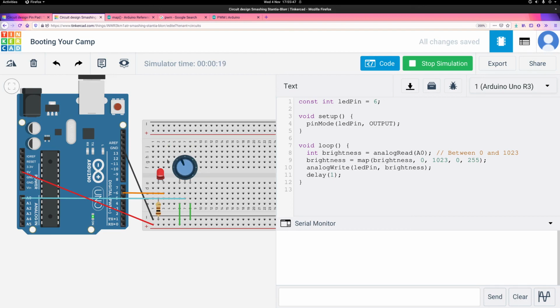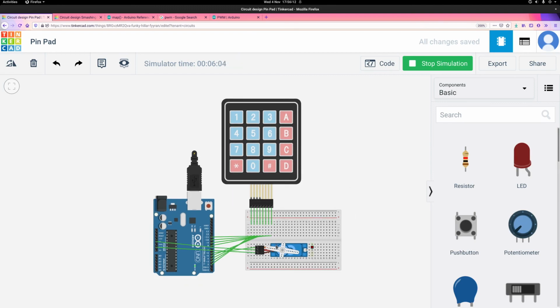Now, there's also probably a way to build this particular circuit without an Arduino. But we've seen already how you can use the Arduino to do more complicated things with the numbers you're receiving here. So, for example, you could use this number that you get from the potentiometer, this value that you twist. You could convert from this big range up here of 1023 into a range of degrees between 0 and 180, and then you could use it to turn a servo motor.